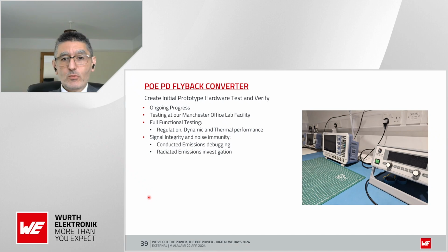The next step was to actually create the initial prototype hardware, and this is ongoing progress. We will be testing this in our Manchester office lab. So we'll do a bit of functional testing first, just to make sure that everything is working absolutely fine. So regulation, dynamic, thermal performance. But we will also be doing some conducted emissions debugging, some radiated investigations as well on the prototype.